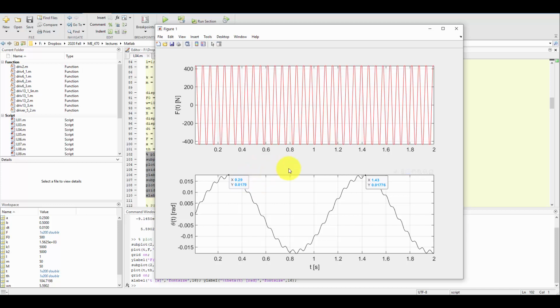And then this shorter time period where we could do this peak to this peak, that is going to be the carrier frequency. And in this mechanical example, that is the driving frequency. But these terms, baseband and carrier, are often used in electrical engineering, where we have some wave happening at these 2 frequencies. Now, I could calculate the time period between the peaks, but instead, I'm just going to look at the power spectral density and reconstruct what I know is the original signal. I know that it's oscillating at the natural frequency and the driving frequency. So let's just make sure we're getting those same results in the power spectral density.